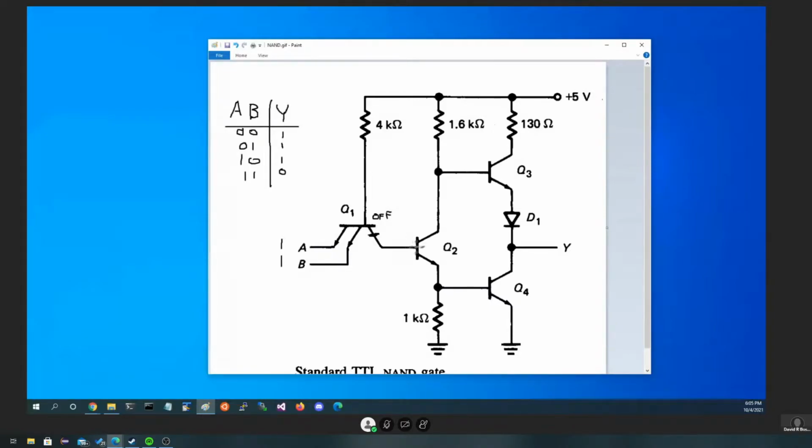Matthew, is that on or off? Q2 would be on. Because we can pull current from 5 volts through the transistor. That should turn this transistor on. Now, if it's on, one of the things we know that's going to have to happen here is this transistor is going to basically have as its collector and emitter the same value. So we'll have to remember that just for facts to know and tell. So this transistor is off. This transistor is on.